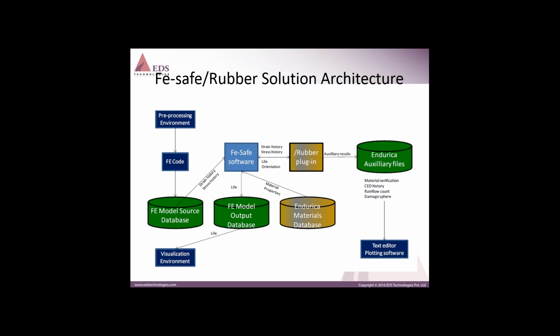Here is the high-level workflow. You will start with your preprocessor environment, where you create your mesh, and then you create and apply loads and boundary conditions. Loads may be forces or displacement.